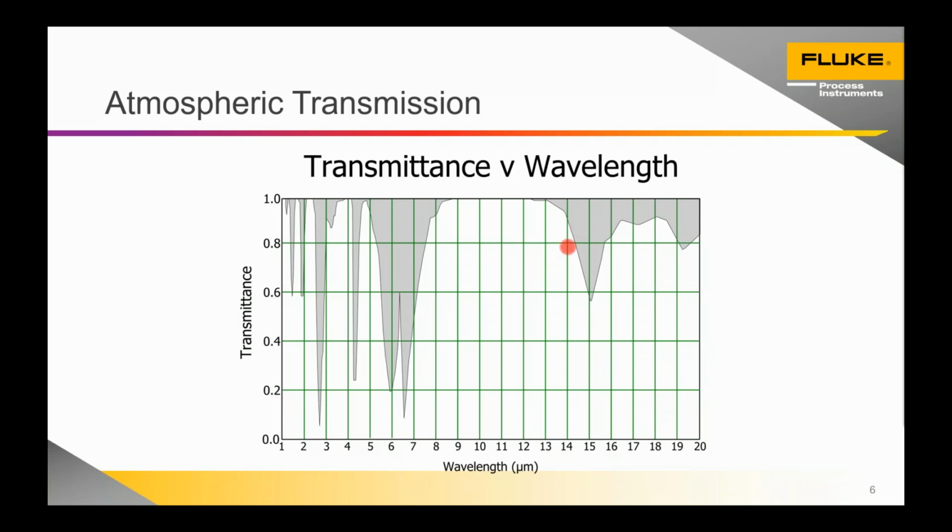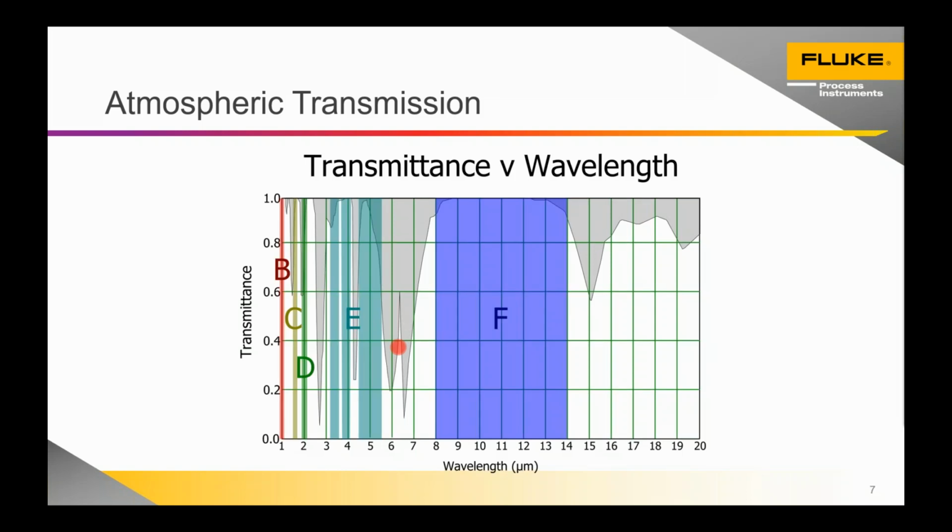If detectors were available, and detectors are available for weather metrology, and we were to use those in industry, we would find that we would have a change in temperature according to the distance from the sensor to the object, and that's something that no general industrial device can really work with, because we have no active way of determining distance. So we choose wavelengths where the air really has no effect.